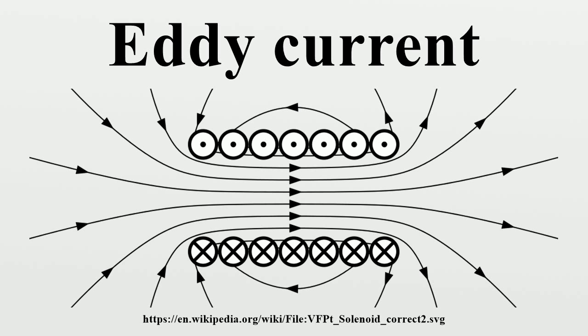The diffusion equation therefore is applications. Electromagnetic braking. Eddy currents are used for braking. Since there is no contact with a brake shoe or drum, there is no mechanical wear. However, an eddy current brake cannot provide a holding torque and so may be used in combination with mechanical brakes, for example, on overhead cranes.